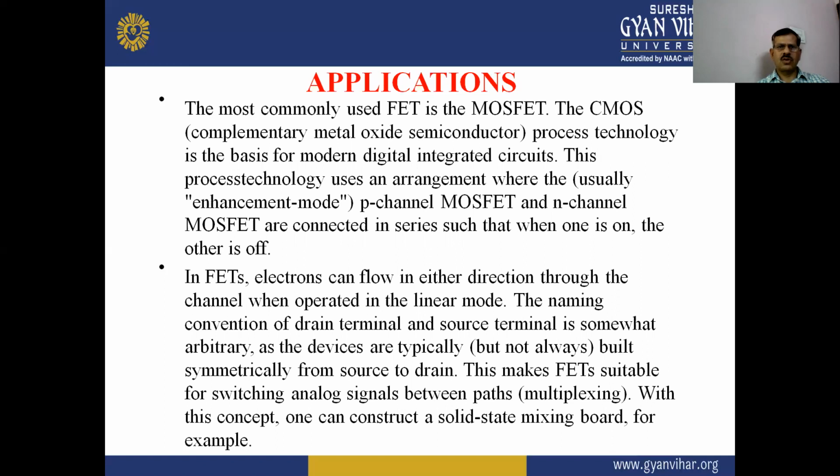So the most commonly used FET is the MOSFET. The CMOS (complementary metal oxide semiconductor) process technology is the basis for modern digital integrated circuits. This process technology uses an arrangement where the usually enhancement mode P-channel MOSFET and N-channel MOSFET are connected in series, such that when one is on, the other is in the off state.